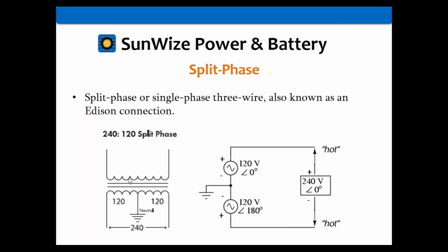You'll notice that on the top side, basically this is the diagram of an inverter, by the way. So keep this schematic symbol in your mind. You've got the squiggly coil on one side, and on the other side, with 2 lines in between, that is a symbol for a transformer. You notice on the top side, that is continuous. That's because that would be a 240 input, so to speak, or whatever the input voltage might be, and that's the 2-wire. So it's a 2-wire input to it.